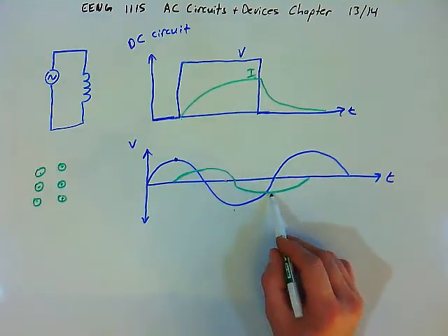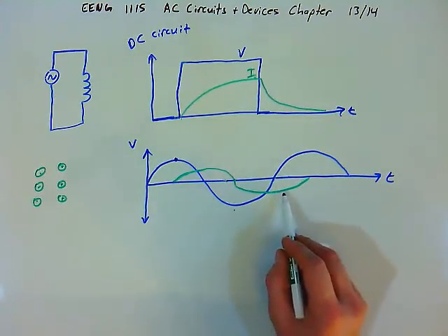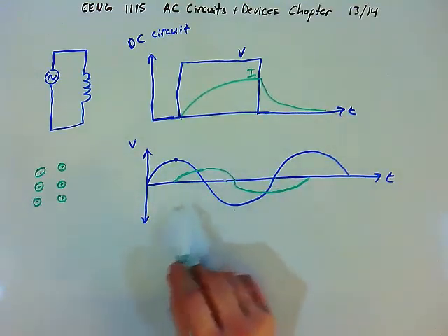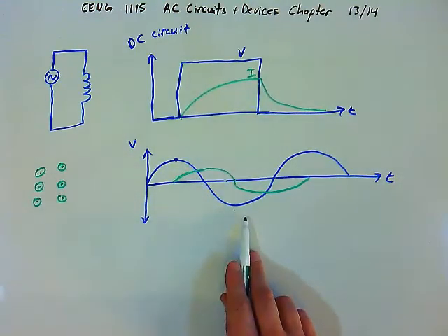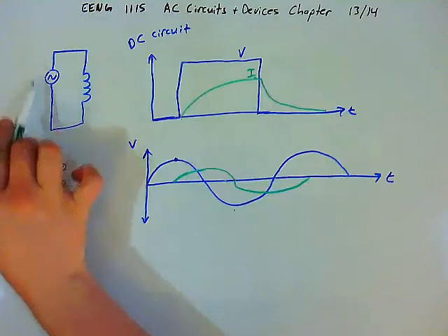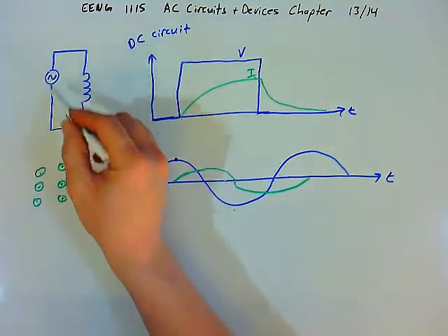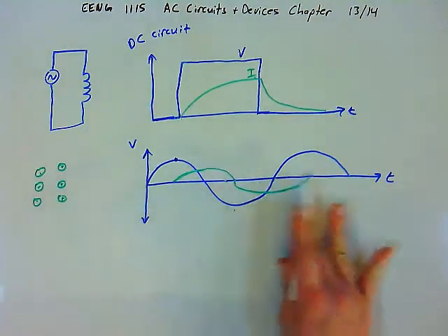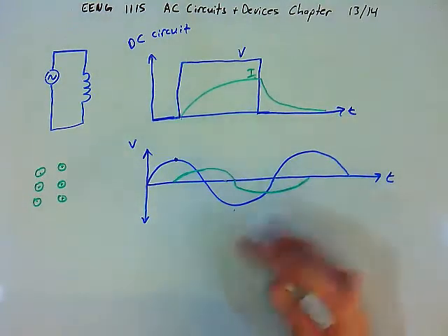And again, at the point when the voltage reduces back to 0, the inductor has stored as much energy as it could, and then it starts to give that energy back. And it tries to keep the current flowing the opposite way through the circuit, right? And by opposite, I mean not forward direction, but reverse direction, right? So remember, the polarity of the voltage is constantly switching. Sometimes current wants to flow clockwise through the circuit, sometimes it wants to flow counterclockwise. And so what we see here is a pattern of two sine waves, essentially. And this will continue on forever.